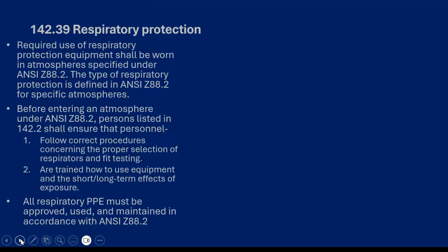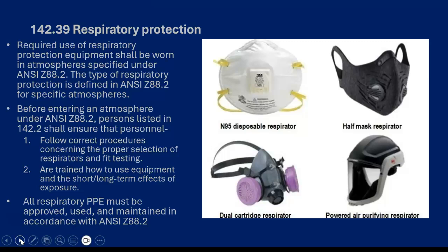All respiratory PPE must be maintained, approved, and used in accordance with ANSI Z88.2. Here you have just a couple different types of respiratory protection: your half mask, your air purifying, and your dual cartridge.